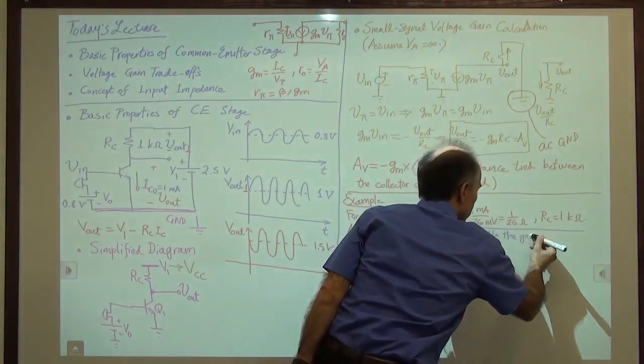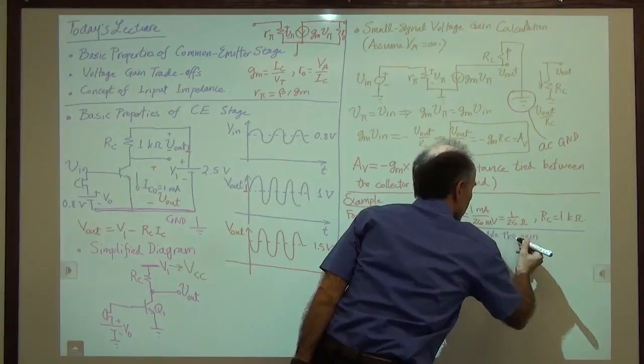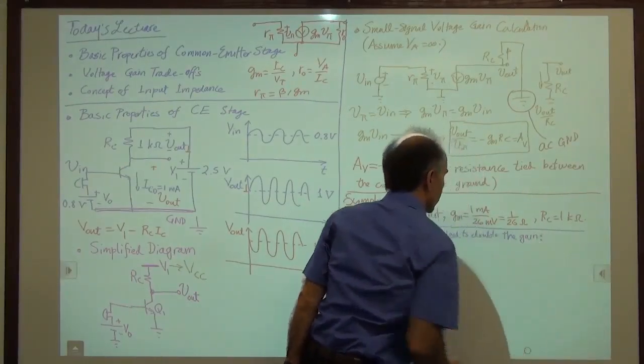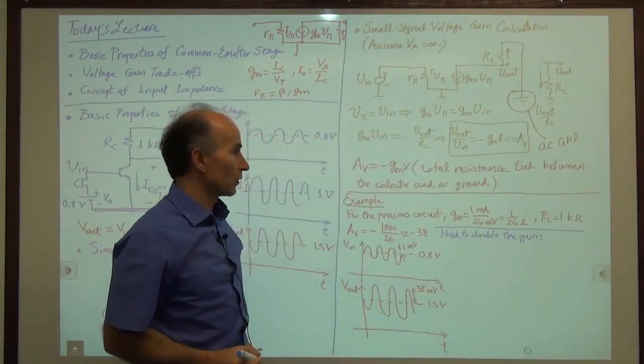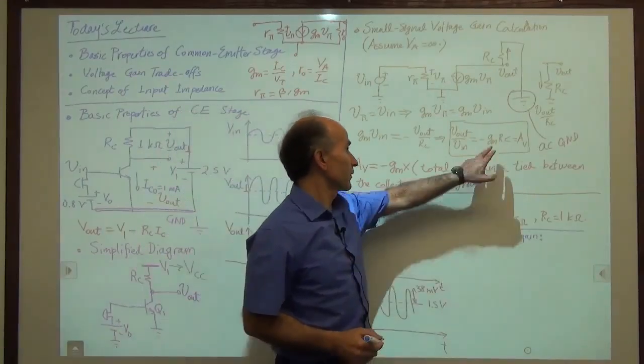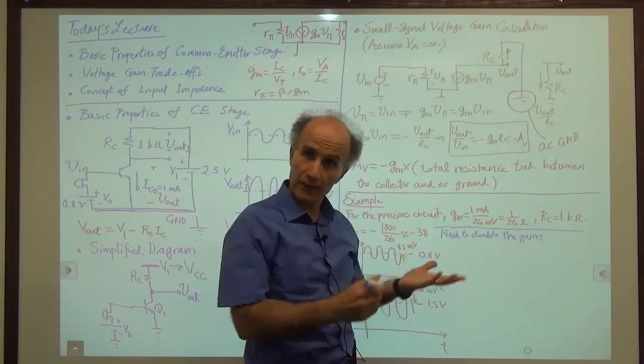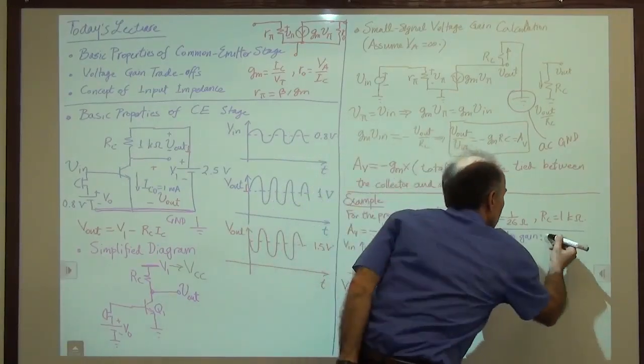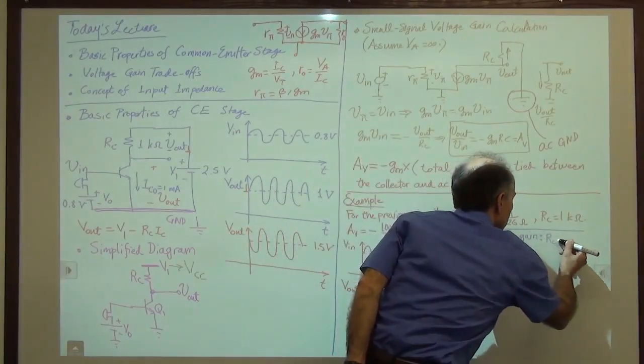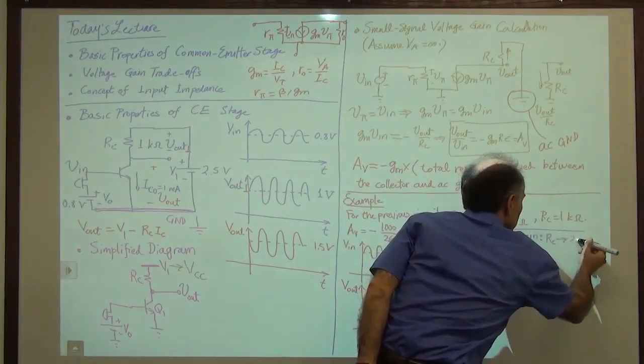Perhaps because the application needs more gain, so your boss came back and said, we need to double the gain. So we said, all right, should we double the GM? Should we double RC? Oh, maybe we'll just double RC, not GM, just as an example. So RC goes to 2RC, right? We double it.